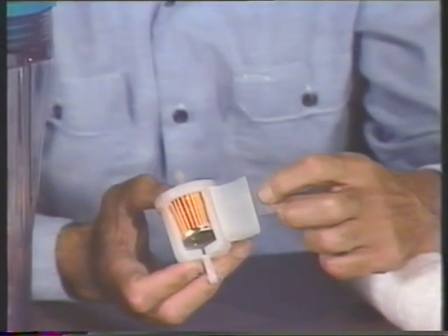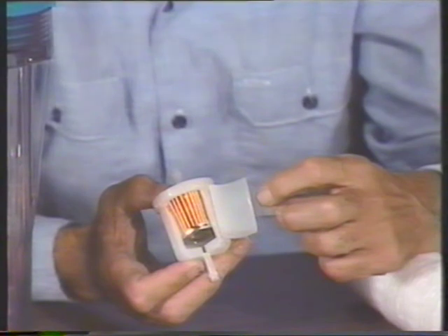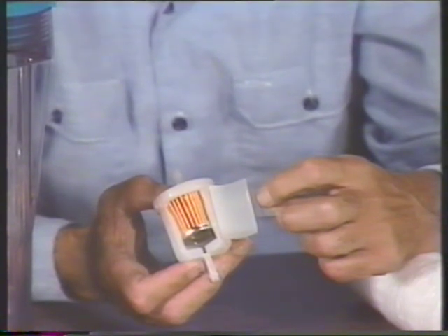Many cartridge filters are designed with the filter medium permanently enclosed in the housing. They're called disposable filter assemblies. This is a disposable filter assembly used to filter fuel. Instead of replacing the filter medium, the entire disposable filter assembly is replaced. This design saves time and helps minimize contact with fuel. In some applications, it's important to minimize contact with fuel because some fuels are harmful to touch. Now let's take a look at a simplified illustration to see how a cartridge filter works.